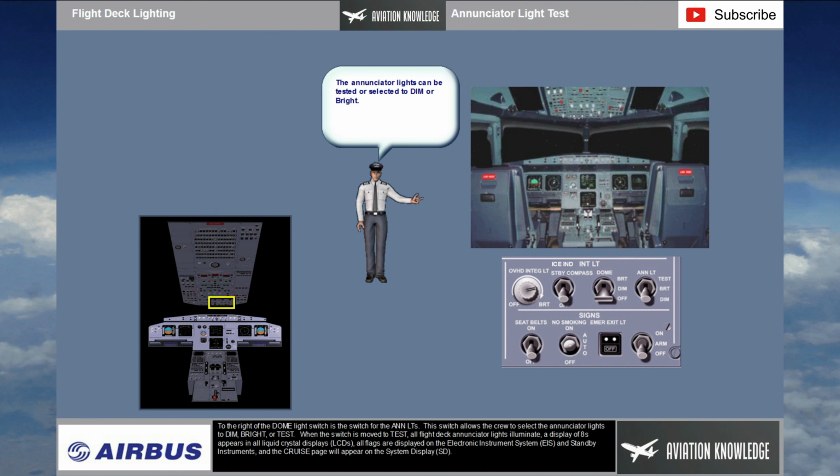To the right of the dome light switch is the switch for the annunciator lights. This switch allows the crew to select the annunciator lights to dim, bright, or test. When the switch is moved to test, all flight deck annunciator lights illuminate. A display of 8s appears in all liquid crystal displays, LCDs. All flags are displayed on the Electronic Instrument System, EIS, and standby instruments, and the cruise page will appear on the system display, SD.